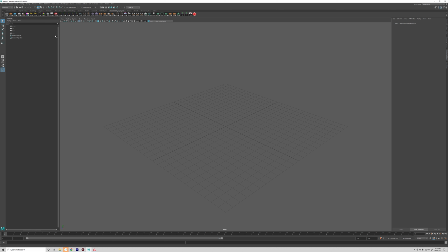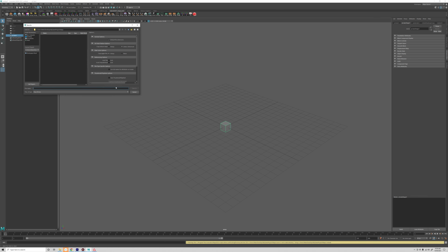What that allows me to do is if I go ahead and model something, so I've got a cube, something in my scene, when I save it, file save scene as, Maya gives us two formats, by the way. I like to change it to ASCII. I just find it slightly safer, slightly more resilient to corruption. Only slightly, it's just a personal preference. When I save it, you can see in my workspace root, I'm in desktop, my game project, Maya. So it's taking me straight to this location, which is really useful.